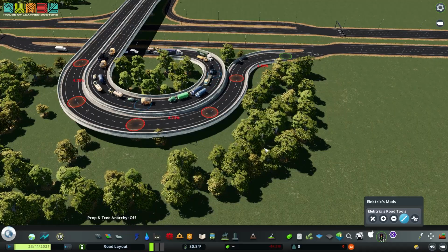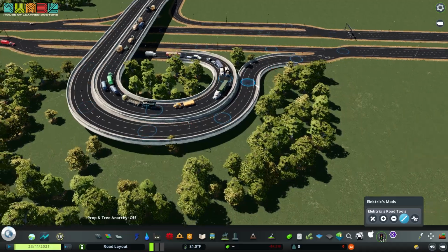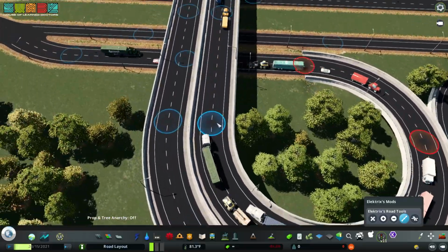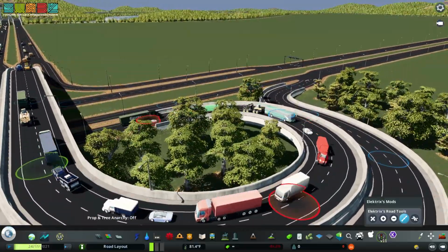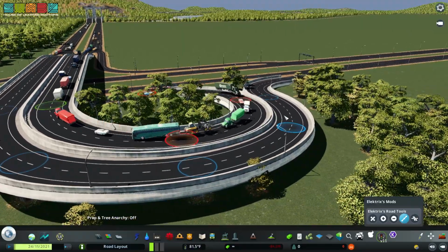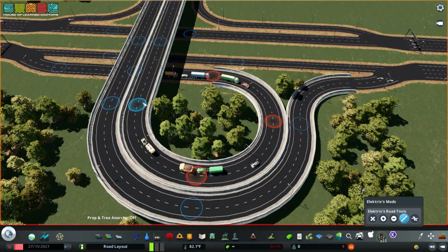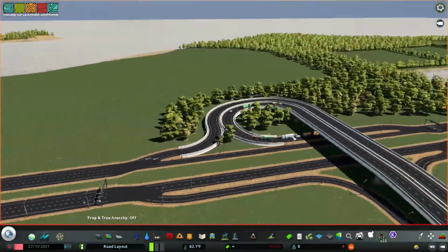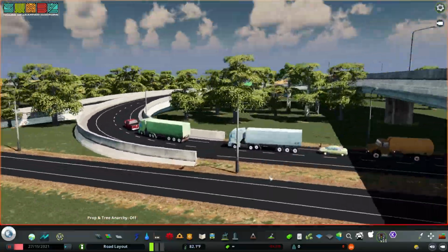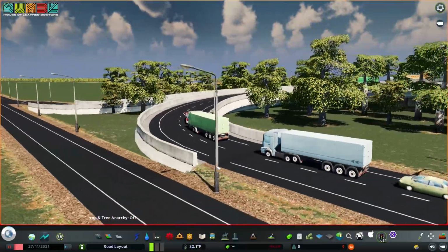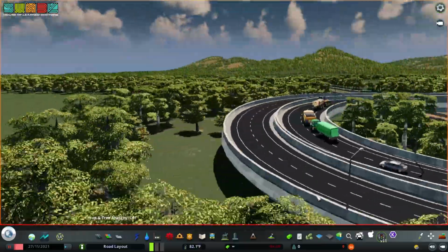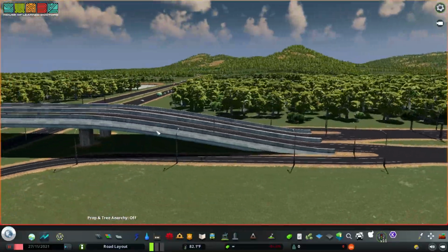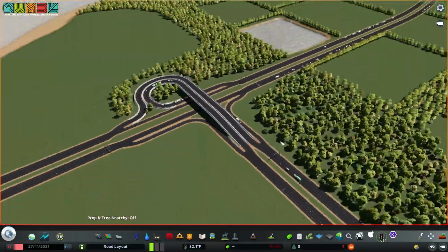And then you do Shift-C to deselect those nodes, and then click the nodes on the other side, because we're going to do the same thing so that these are equal. Hit enter, and look at that. That one should literally not change. Cool. So now we've done quite good. I think it's a very clean-looking result as far as going up in grade from here up to 12 meters over a 5x5 curve that goes all the way around. This one doesn't need to be resloped, really, so that's fine.